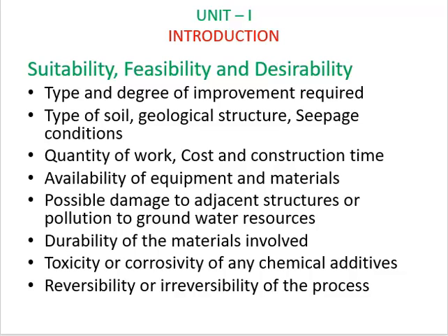Next point is possible damage to adjacent structures or pollution to groundwater resources. While operating the compaction equipment at the site, care should be taken to avoid damage to the adjacent foundations or structures. In case of chemical stabilization, even the chemicals should be carefully chosen to avoid pollution to the surrounding water resources.